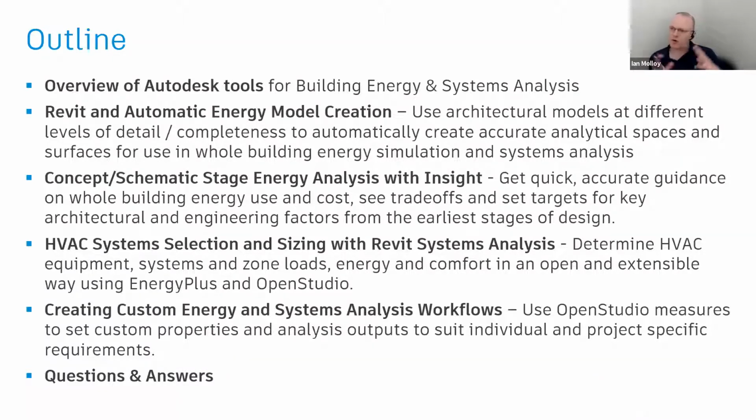My goal here really is to orientate you on all the things that are available and help you understand how you can get started and the kind of things you can do with them. So to break that down a little bit more, I'm going to talk about some of the key aspects of the workflow. One of the main ones, where everybody starts and also commonly gets stuck, is energy model creation: taking a typical Revit architecture model or other starting point and creating an energy analytical model from there, the geometry, so to speak. And then the other aspects of that around the energy settings and the different metadata that's associated with that model in order to run an analysis.